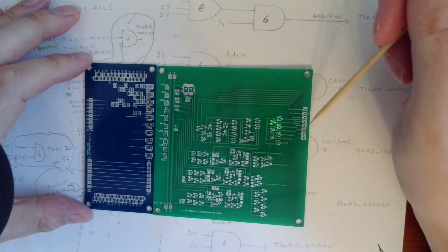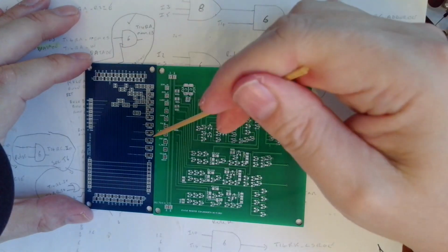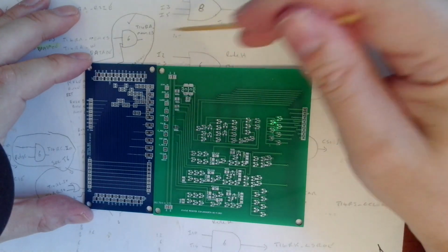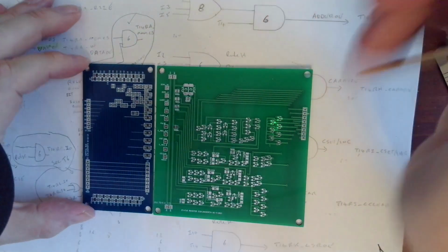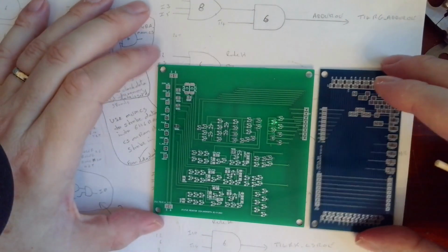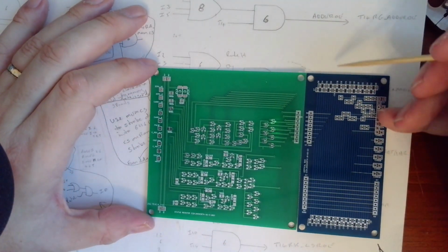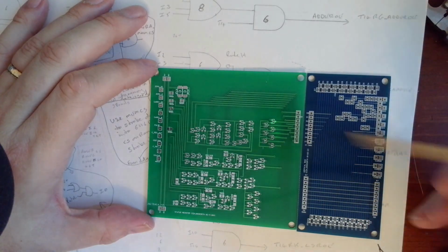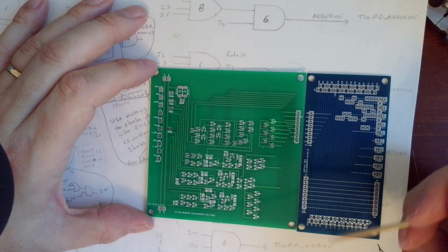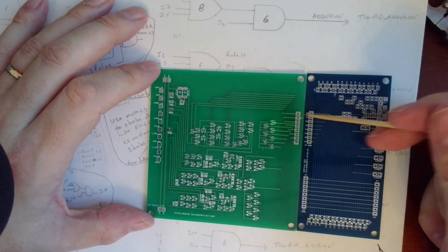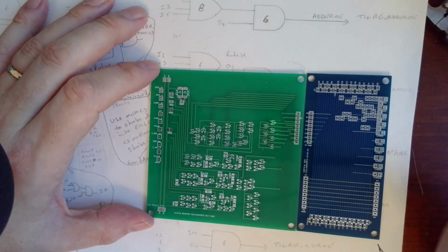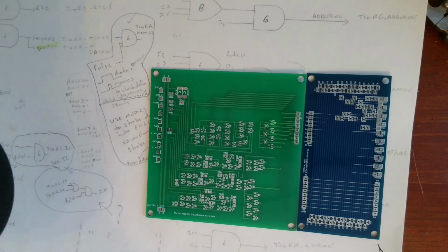The C register doesn't actually feed onto the data bus at all. It goes back out on its own control signal dedicated to go to the adder. So this would also be on that side, another one. So your data comes down here and will feed through out the bottom to other registers, or there's your data bus there, so you can connect links straight across there.